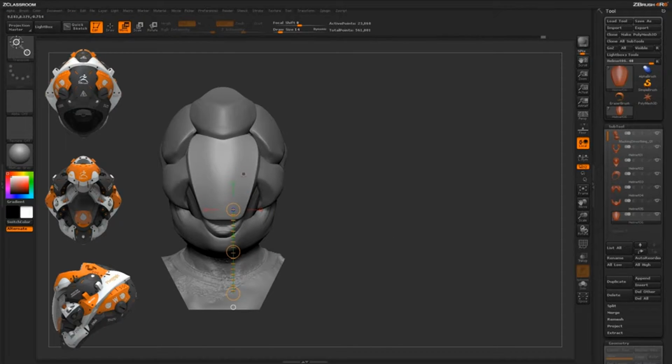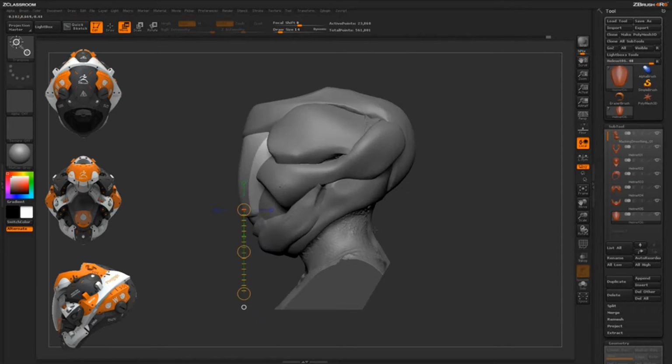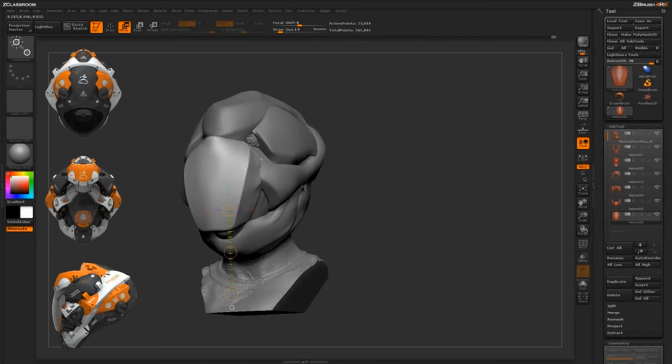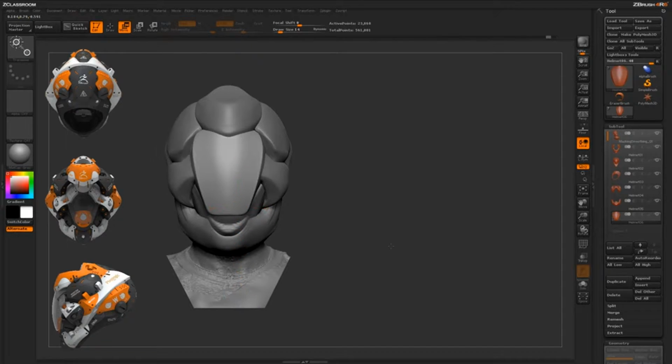So this is really nice for kind of just doing quick moves on things or nudges. So I can just come to a certain angle like the front view here and hold Alt while being active in the move transpose line and then just move that part around. So if you need to just come in and do quick kind of adjustments to things, you can do it really quick with just that screen space or canvas space movement.